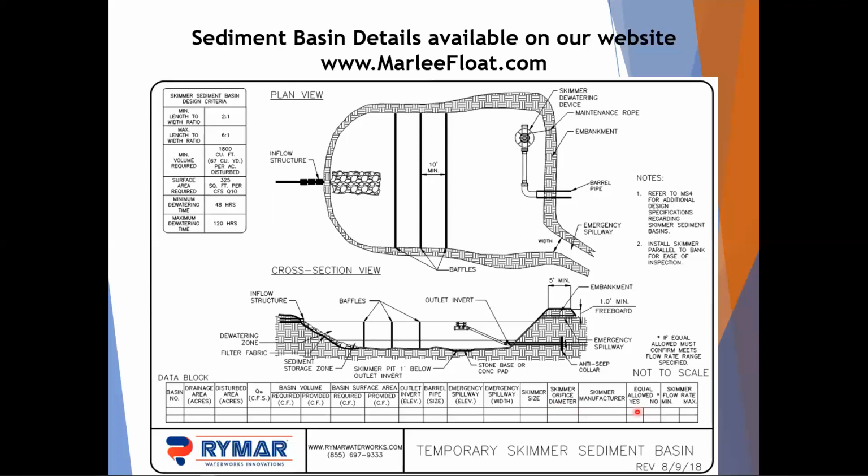Most of the time that's going to be yes. We encourage everybody to be on an equal playing field. However, there may be times where you've got a site that you really want to make sure you've got a precise flow rate, and you need to use the one that's been set. Or you can just set a minimum or maximum flow rate. In that case, let's say you specified a Marley and the contractor said they want to use a different brand. Well, as long as the flow rate for that skimmer falls within this range, it's already been approved by the reviewer. So it's a simple kind of shop drawing review, not a full resubmittal or redesign kind of thing.